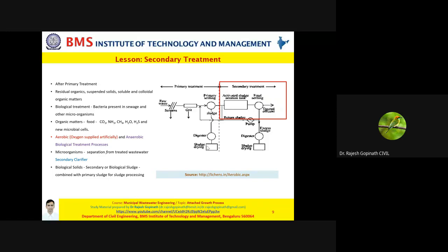Yes, there may be a certain quantum of sludge produced, let's say in the context of ASP, in the aeration tank itself, but it is always desirable to remove it, because your trickling filters and aeration tanks are not meant for settling of solids. If that happens, it would disturb or impair the functioning of your trickling filter or your aeration tank.